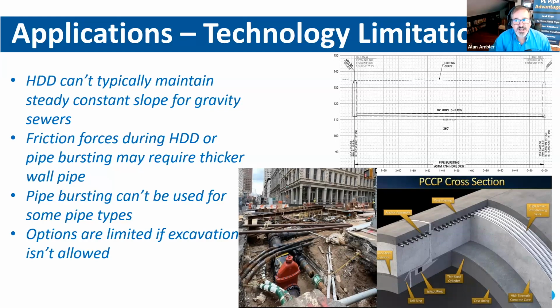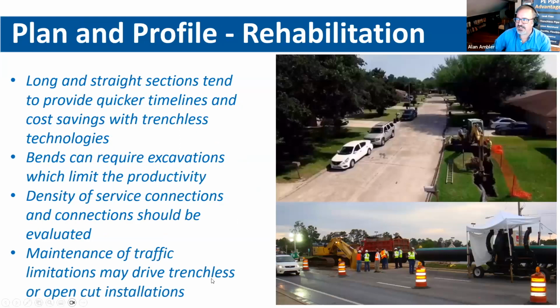The ones that we're not going to be able to burst are going to be a heavily reinforced concrete pipe, ball and socket ductile iron pipe, the pre-stressed concrete cylinder pipe that you see. The ones that are troublesome are going to be ductile iron, more younger generations of ductile iron, and then also corrugated metal pipe as we go through. So we do have a whole pipe bursting webinar in more detail for you on our YouTube channel, which a lot of people definitely take a look at. You can always shoot us a note to see if you got something special.